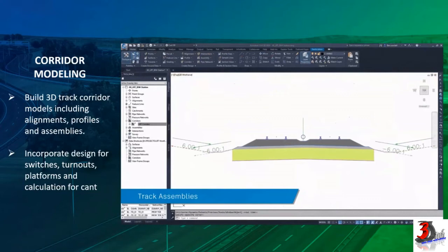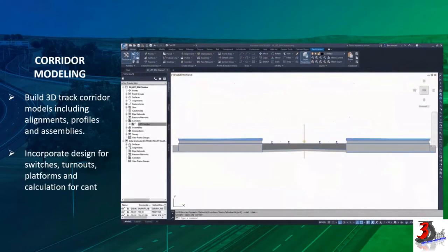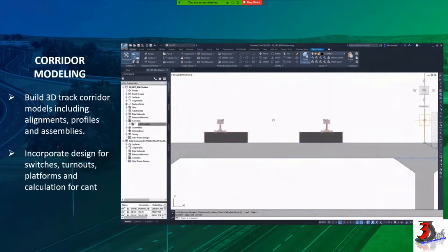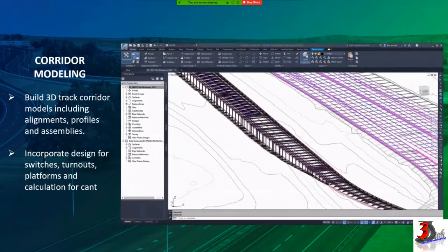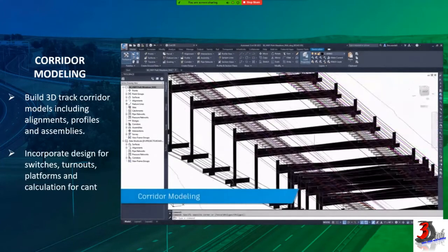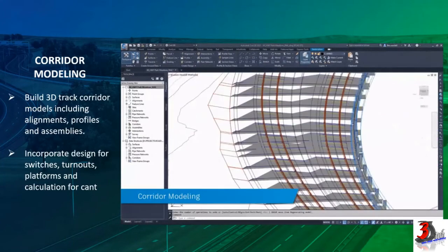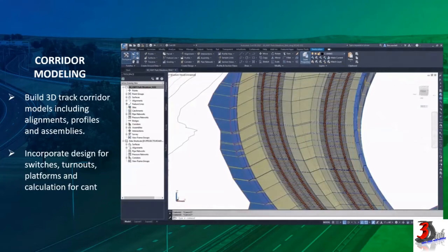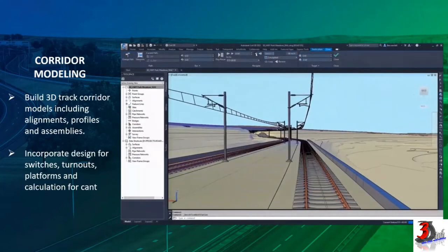Corridor objects include corridor body geometry, longitudinal feature lines, embedded surface, rendering support, and slope hatching support. After you have created a corridor, you can extract data from it, including surfaces, feature lines, polyline alignment, profile, and grading features.